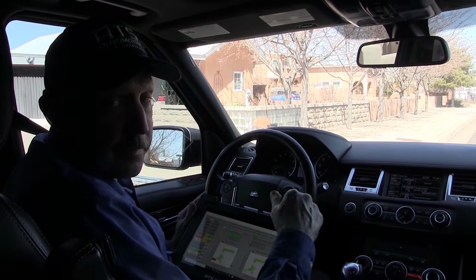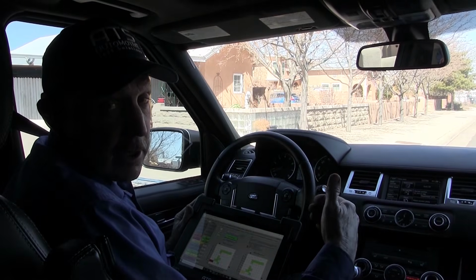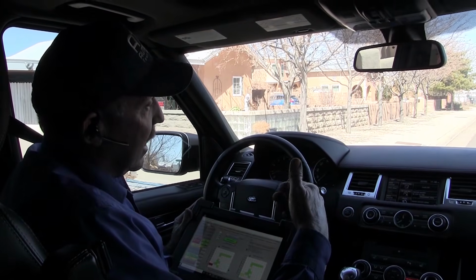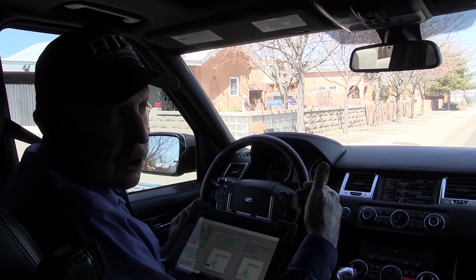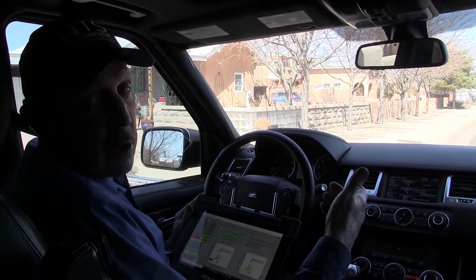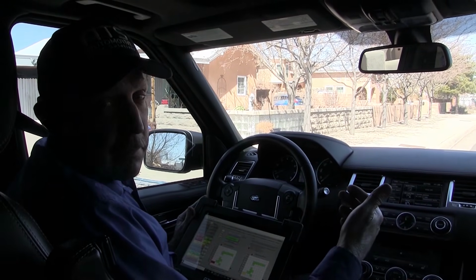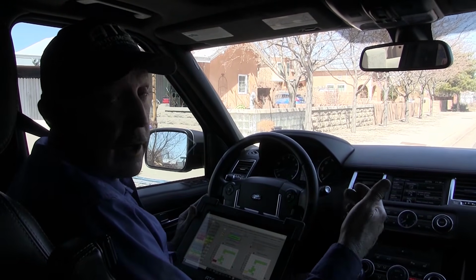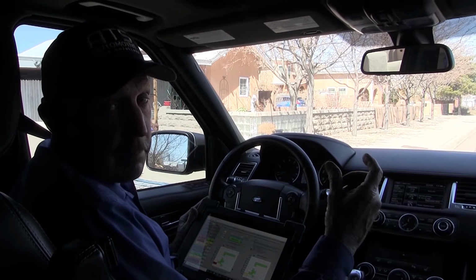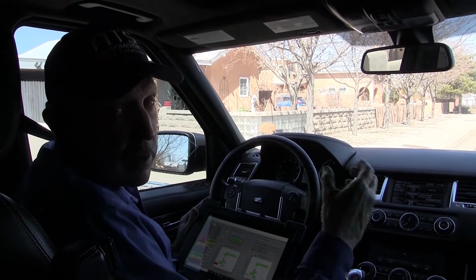In other words, the way trim is done is it's by fire cycles by the trim authority. So let's say the program would say that I would have 100 fire cycles or 200 fire cycles, and for every 200 fire cycles, I could add 0.25% trim. That would be one strategy. That's why some cars like GM and Toyota have real rapid trim changes, because they have fewer fire cycles to more trim authority.